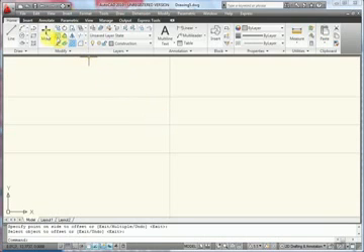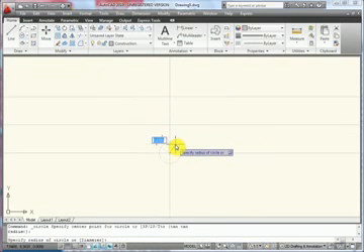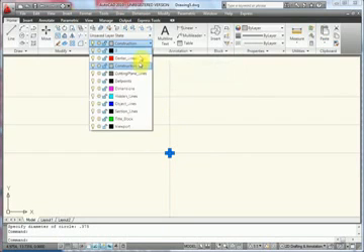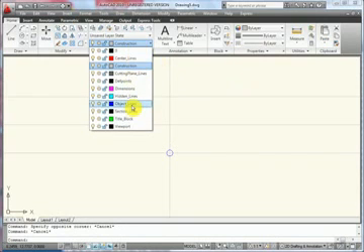And now I'm going to go to the circle command in the draw portion of the toolbar and use the center radius circle. I'm going to start off with a circle that is a diameter, so I can input a D of 3/8, which is 0.375. Now I'm in the wrong layer right now, so I need to correct that. So I'm going to left click the line I want to change and now change it to the proper layer. Once I've changed that layer, I'm going to deselect everything by pressing the escape button on the keyboard and switch to my object layer.